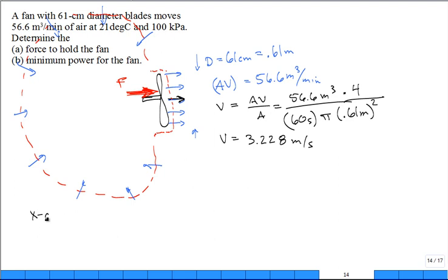We do the x direction linear momentum equation. We have F in the positive x direction. It's equal to, at steady state, the inflow, but the inflow has negligible momentum coming in. Does that make sense? Because it's all coming in very quiescent over a large area. And the exit? It's all coming out over a concentrated area. So it's equal to beta, which is 1 for this problem, times the exit speed V,